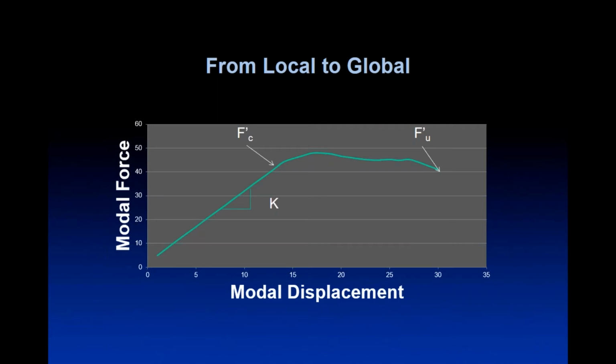So if we take a calibration at this point and we use our measurements of frequency and damping, and we compare what we're measuring of a structure as it is in the field, and then compare that with what the code of practice tells us it ought to be, then we've got that ratio between as is and as it should be if it's redesigned new. Okay, as it should be. That means that we've got to have predictors of what it should be for a structure in good condition.